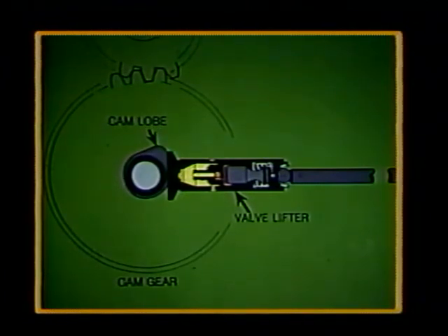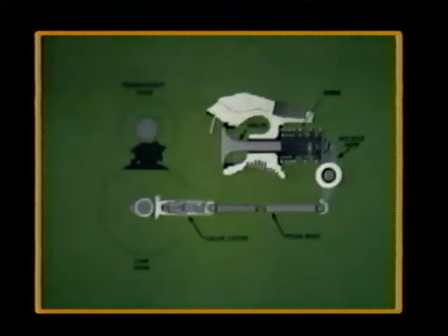As the valves are pushed open by the rocker arms and the push rods, the cam followers ride up on these lobes. Then, as the cam followers ride down on the opposite side of these lobes, the valves are closed from the pressure of the valve springs.